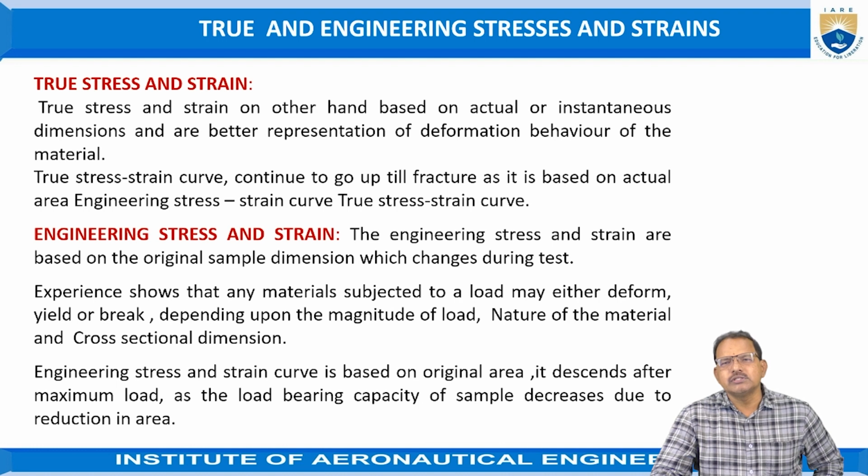But the true stress-strain curve is obtained by drawing the relationship between the stress and strain, where the stress is force divided by the instantaneous area of the cross section. When the load applied increases, the area of the cross section also changes continuously. Hence, at every moment the stress has to be determined to plot the diagram giving the relationship between stress and strain.